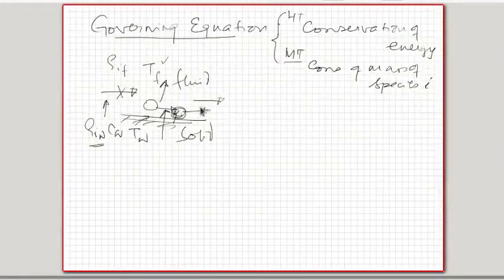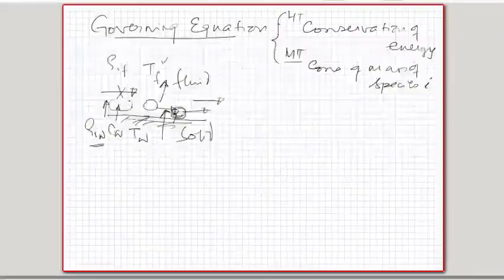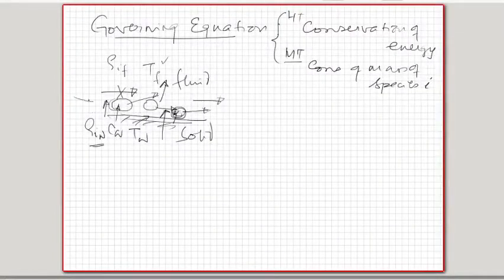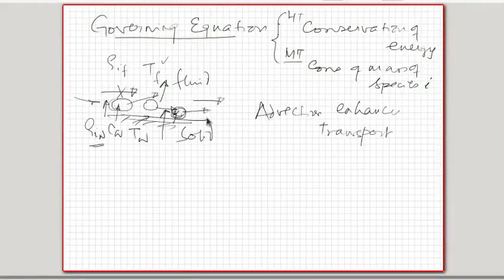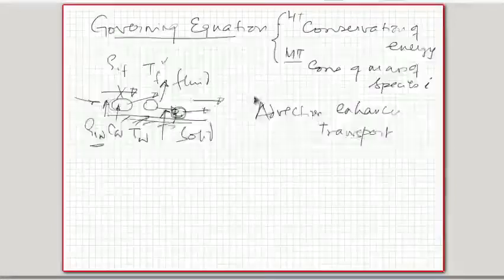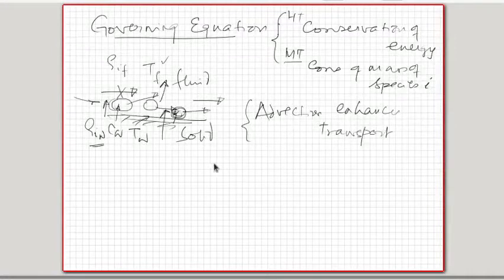So normally what happens is the heat transfer gets enhanced by the presence of fluid motion. So there is always an increase in heat transfer because of the fluid motion. In the same way for mass transfer. So suppose a certain amount of the salt has diffused from the surface into the fluid element that was here, and this has moved away, and another fluid element takes its place, which is closer to rho I F than to rho I wall. So there is a potential to increase the mass transfer. So advection enhances the transport. Okay, so heat transport is enhanced by the presence of advection, and similarly mass transport is enhanced by the presence of advection, and therefore advection enhances transport.